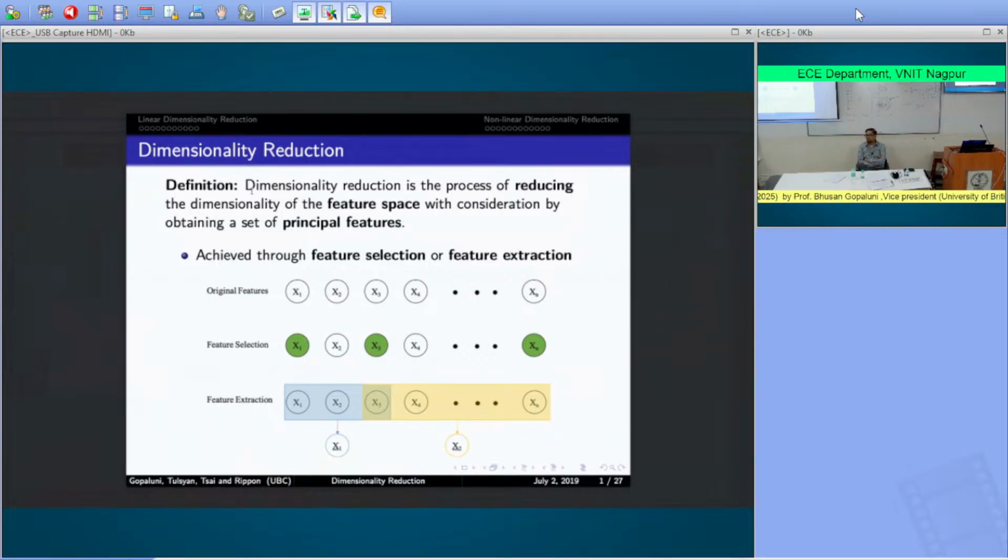Right? So for instance, you may have 3 temperature sensors on the same process. Or you may have multiple flow sensors on the same process. And when you collect data, you have all of this data, but the information in some of these measurements is similar. It's sort of duplicated in those measurements, right? And if you use those high-dimensional data and try to build models, you can sometimes run into issues around singularity of inverting matrices, etc.